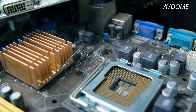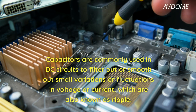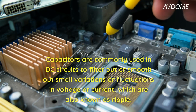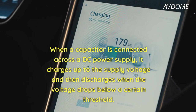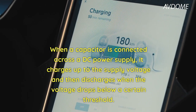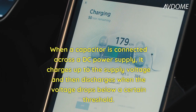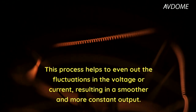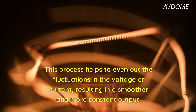It is B. Capacitors are commonly used in DC circuits to filter out or smooth out small variations or fluctuations in voltage or current, which are also known as ripple. When a capacitor is connected across a DC power supply, it charges up to the supply voltage and then discharges when the voltage drops below a certain threshold. This process helps to even out the fluctuations in the voltage or current, resulting in a smoother and more constant output.